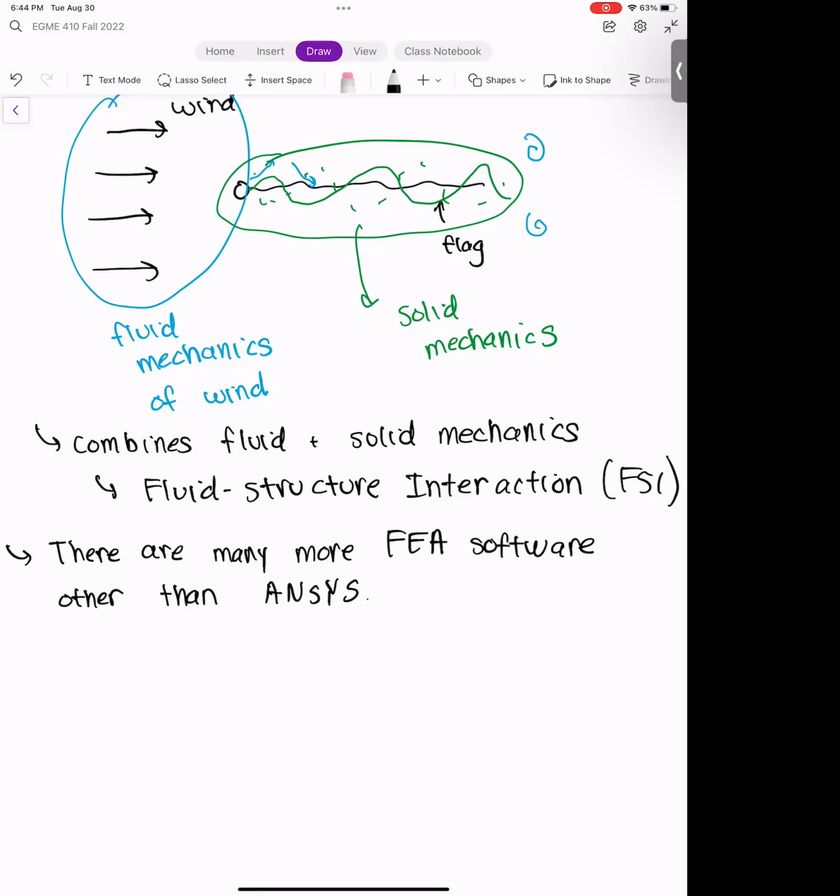I think what might have happened was that when we made the geometry, remember one of the first things you do is change it to 2D. If you don't change it to 2D, it's a 3D simulation that you can only apply pressure on. So I would double check it. The unfortunate thing is that you can't do it retroactively. You kind of have to start over. Just make sure you have that option.